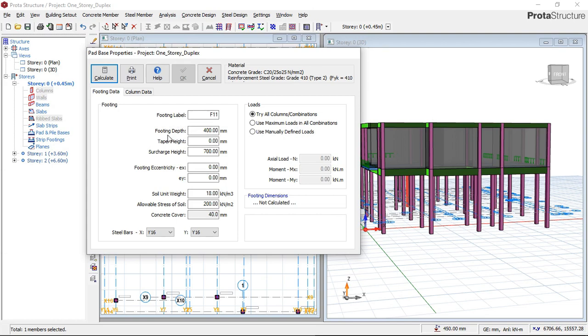Sorry, your footing depth. Your footing depth is always assumed. So you as the structural engineer will assume that footing depth. Now what happens is that on your assumption, you will be guided by some principles. So I always advise that your minimum depth for your assumption should be 250 millimeter. So right now, I'll use 250 millimeter as my first initial footing depth and my first assumption. And if it is not sufficient, then we can go and increase.